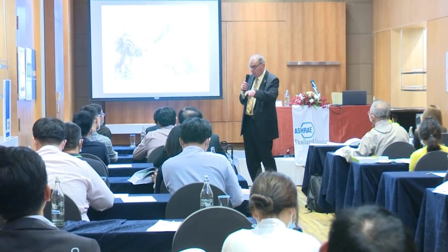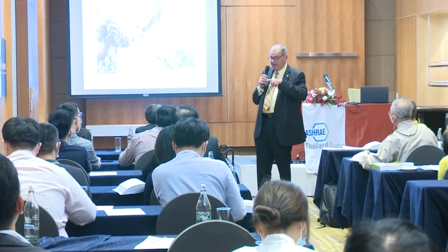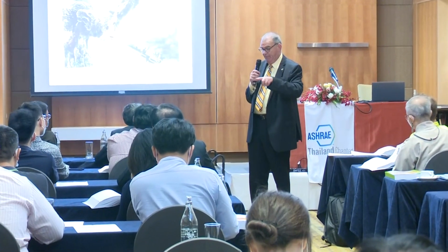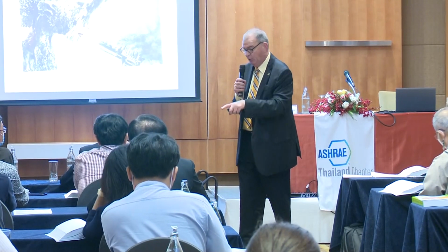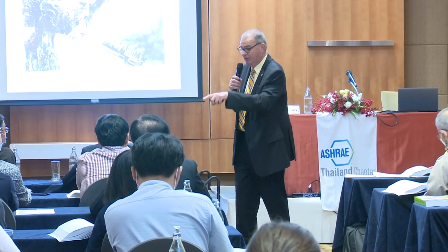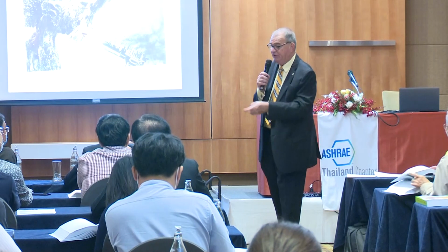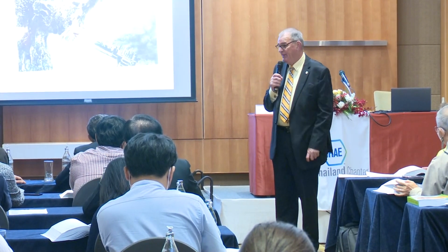Because, you know, it's a square duct, but you start here on this end, you go in a little bit more and you get that flow, go in a little more, you get that flow, go in a little more, you get that flow. So you have to get the velocities at all the different locations inside that duct. And that's why you have to do that.